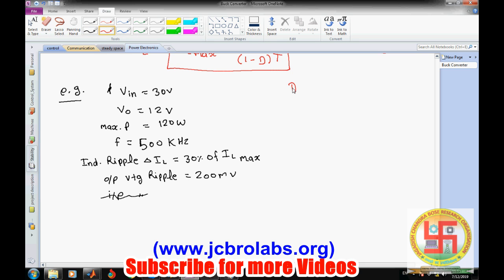So let's first find D. D equals V out by V in, so it comes out to be 0.4. Then I out, the maximum output current, is obviously P divided by V out, and it comes out to be 10 ampere.